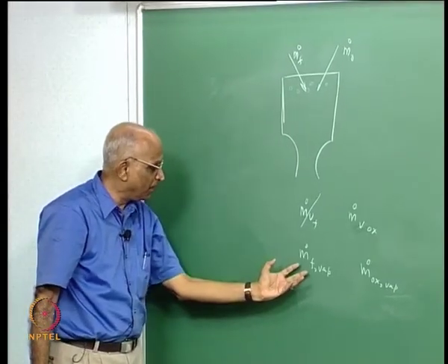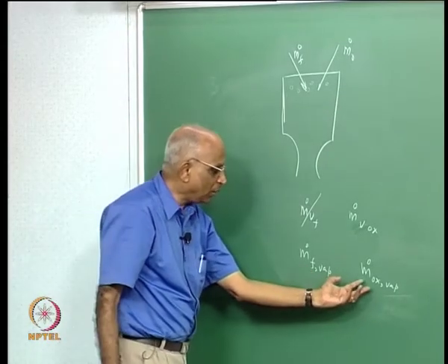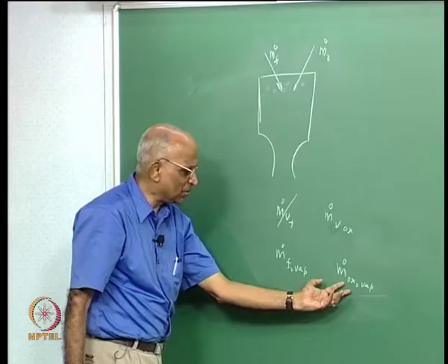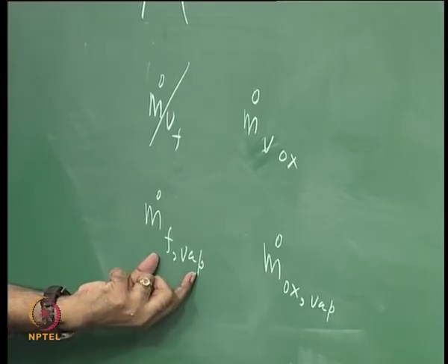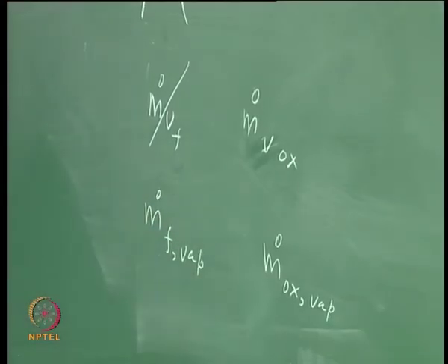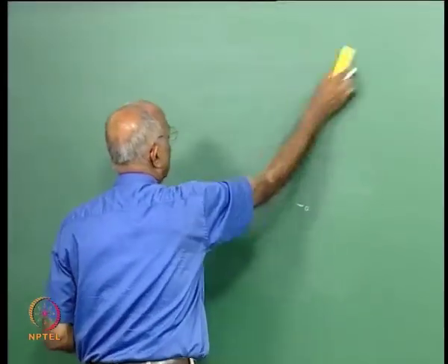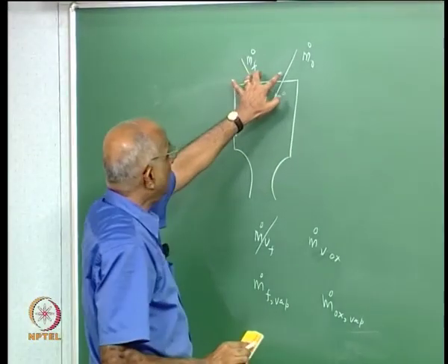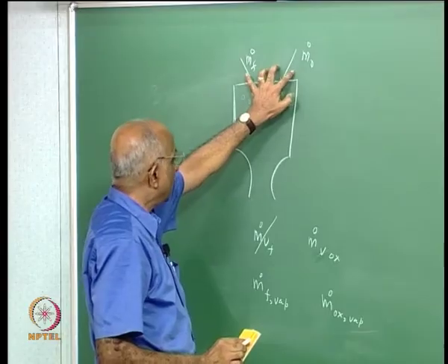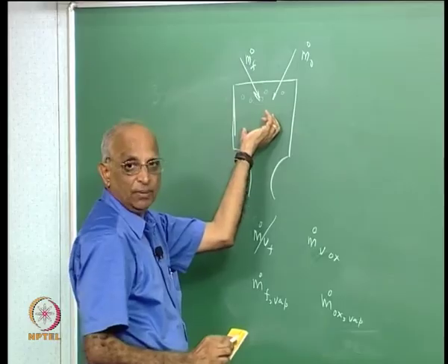Therefore, it is quite possible that not all the fuel which is injected vaporizes, and not all the oxidizer which is injected. Maybe just after this, I will tell you what is the time taken for things to evaporate. Let us do that exercise also. Now, if I have to calculate that, how do I do it? How do I calculate the penalty I pay if all the liquid fuel and all the liquid oxidizer which I inject into the chamber does not evaporate, mix and burn?